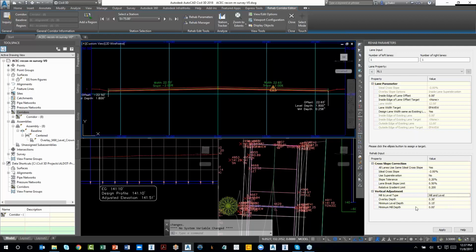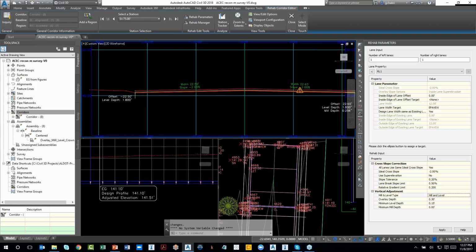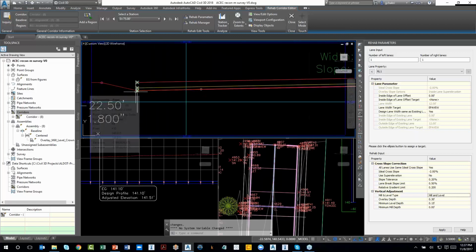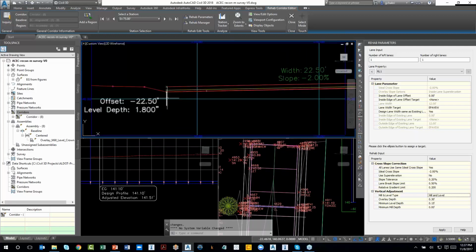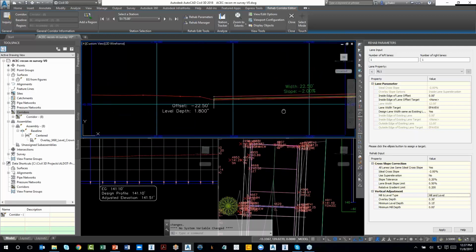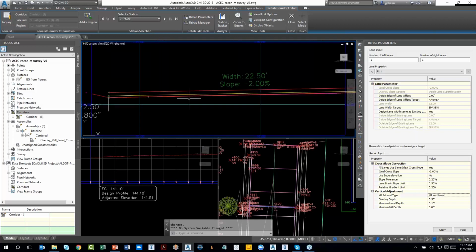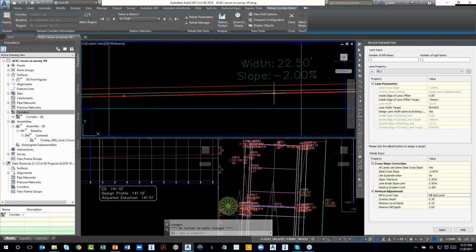apply button, you see that I chose minimum mill depth as 0.0. So basically I wanted to look for the lowest point on the existing pavement, right? I think that condition happened here. And from here I create, using the cross slope that we calculated, 2%. So we apply a 2% slope towards the crown from here, right? And now the mill surface and level surface are parallel to each other, because level is now off of the mill surface, and we specified a depth of 0.15, so it is going to be parallel to that.